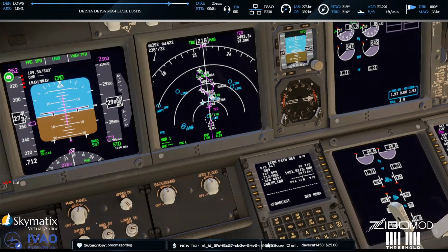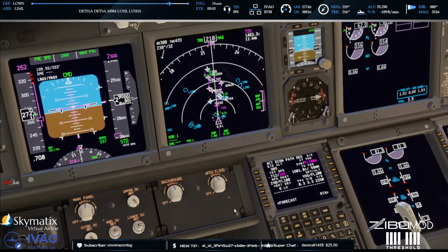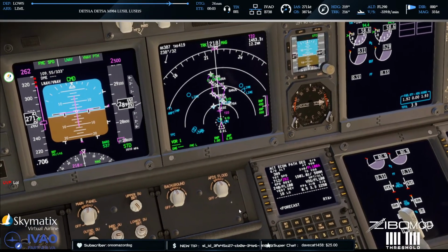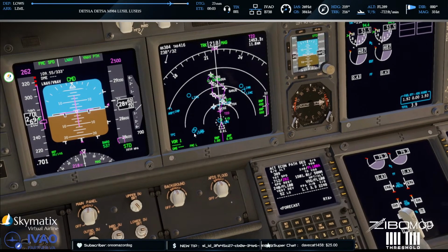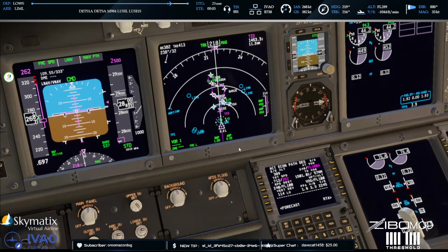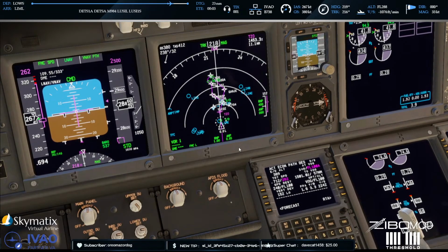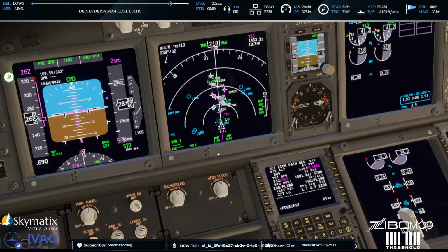I was thinking because it goes into the 1,000 feet per minute descent, doesn't it, until it matches your V path. Yeah, the last ATC flight we did online here, I don't go there and press Descend Now. I just press Alt Intervene. It does the same thing, you know. So at least now they know where to go and look for this.